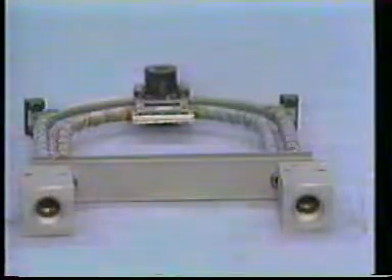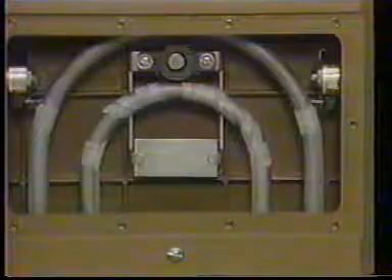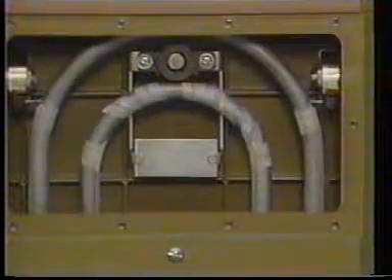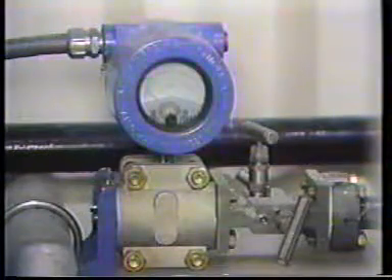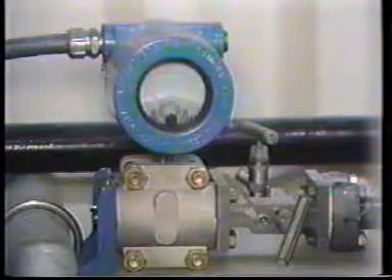There are basically two ways that mass flow is measured: with a mass flow meter or with an inferential mass flow meter. A mass flow meter is a flow measuring device in which the reaction of a sensing element is proportional to the mass flow rate. An inferential mass flow meter is a volumetric flow rate measuring device whose output must be converted to mass flow.